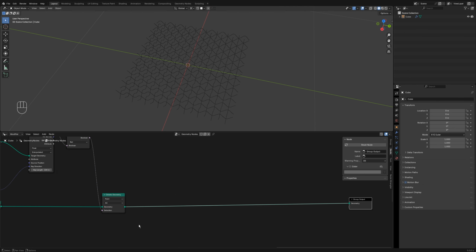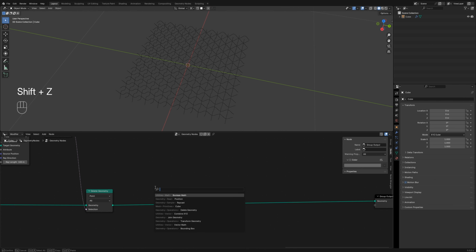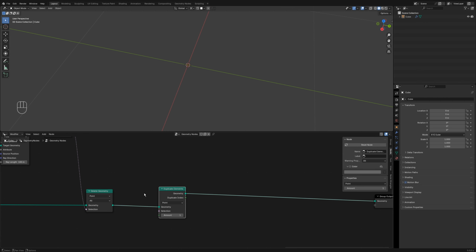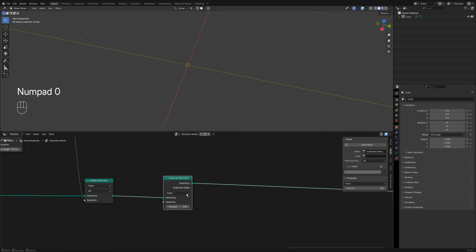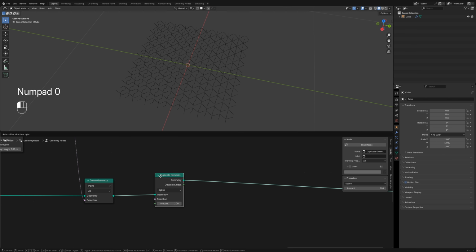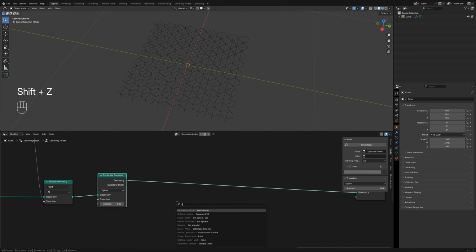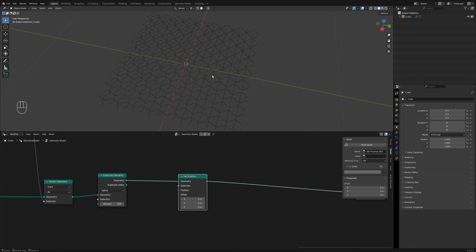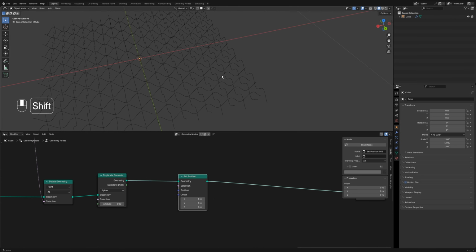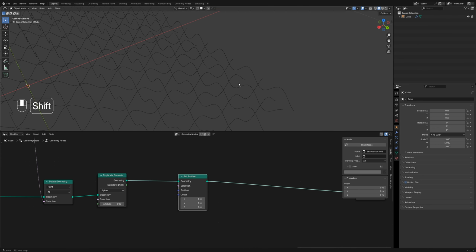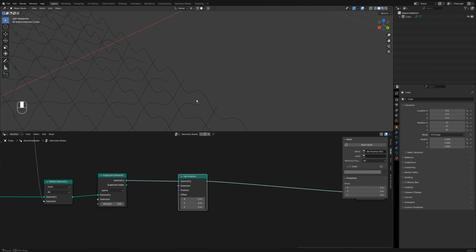Now we need to increase line quantity. First duplicate splines, but they all stay in one position. We need to offset each line left or right. How to set left or right vectors? We can use cross product.